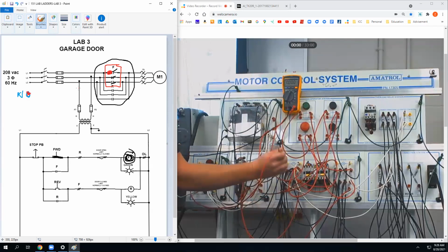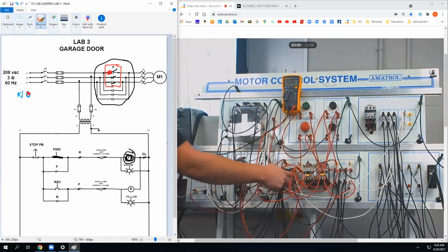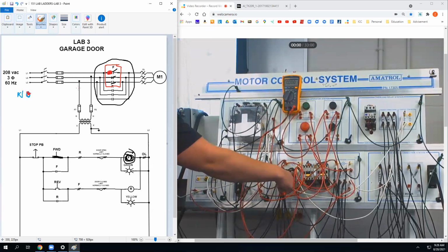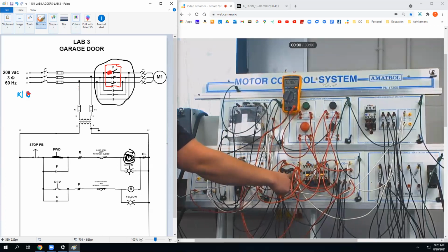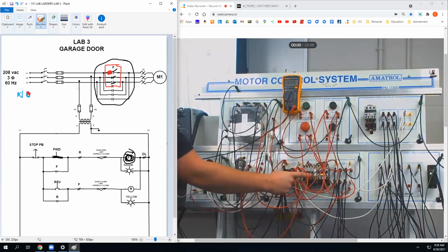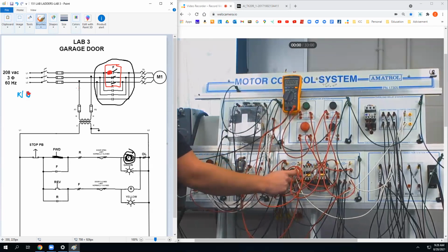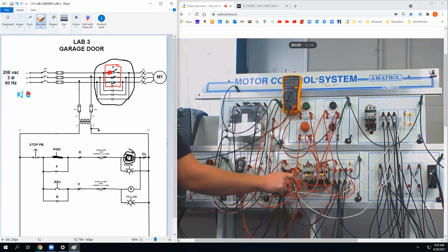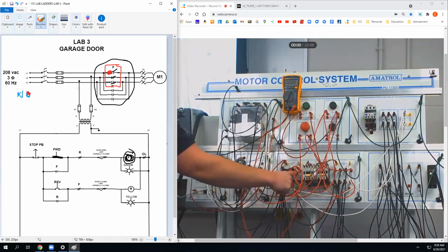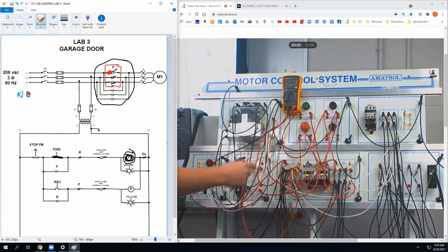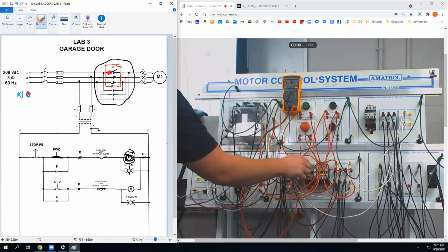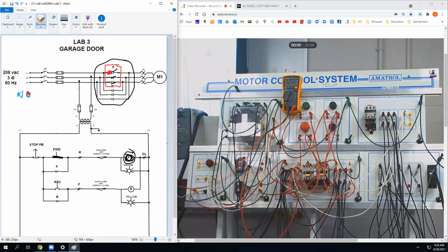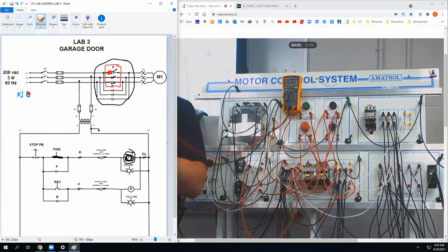Basically on this, it's jumbled for good measure. But this L3 right here is a normally open contact, and when the contactor coil pulls in, it should close, right? Yeah. So I got 120 volts on top, and with it closed, I've got nothing on the bottom, basically, which means this thing is either not closing or the contacts themselves inside this contactor are dirty, or they've been arcing and they're not making good contact, right?